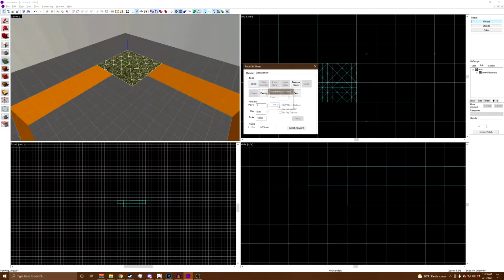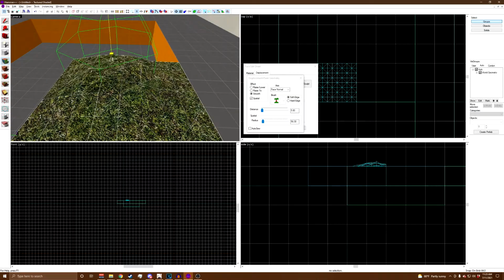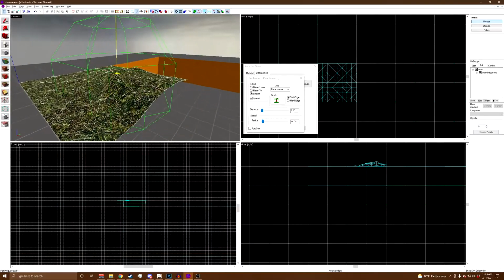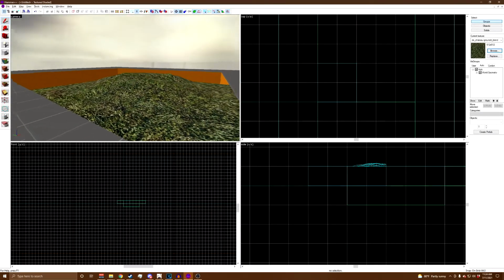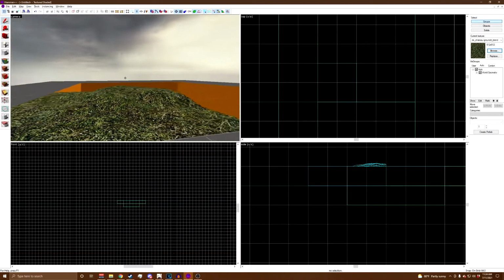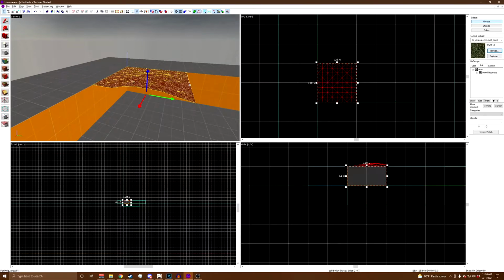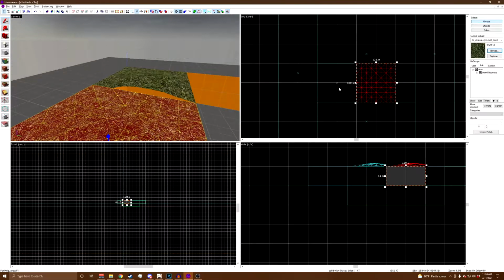You only want to select faces that you plan on sculpting. Rule number 2 of displacements: displacements can only be 4-sided shapes. Triangular sides, for example, cannot exist as displacements. Rule number 3, make sure that all adjacent displacements are sewable with each other.